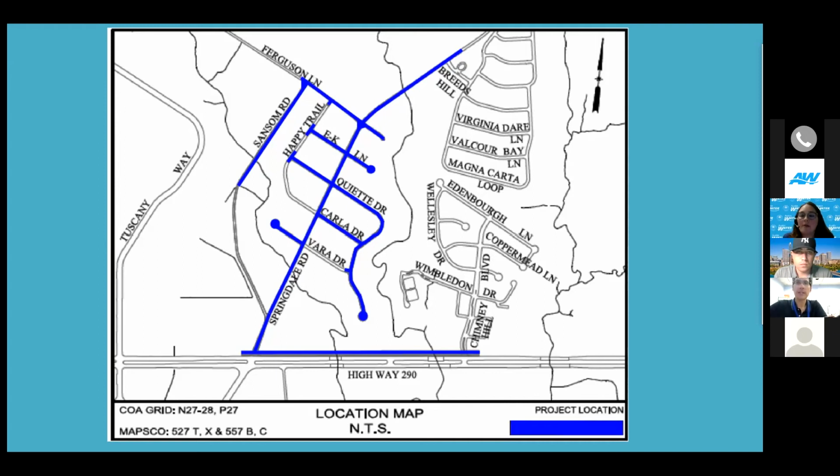Joe, just to go ahead. I was just going to ask a follow-up. Once these system pressure reducing valves are in place, will individual homeowners need to make any adjustments on their PRV that's at their meter or on their property? I don't believe so. I think whatever the setting is now can just remain to whatever it's set at.